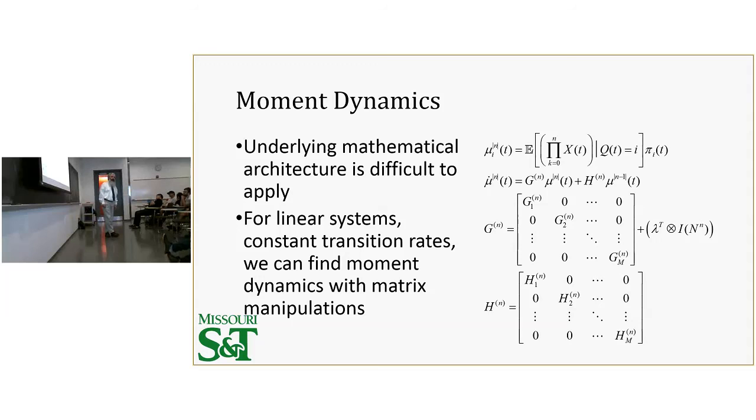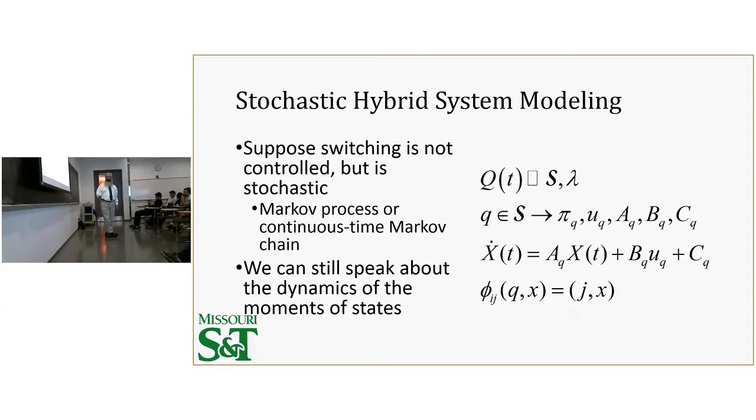But what about the reset maps? Do you have reset maps here? So it's just that they are not there. Right. The reset map that we would have needed in the other is lumped into this C matrix. So again, we keep X, our continuous states, smooth, and then we change this C to deal with that.